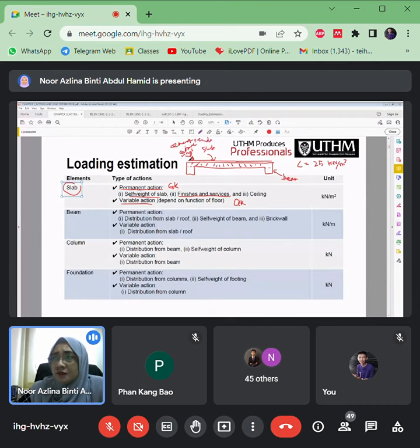So all of these give a load also to the slab, per area. So that's why we have to consider the finishes, and also services. Maybe this slab also has piping inside of it, and then we also consider the shielding. Normally it will be hangings below the slabs here. So these are all examples of GK, examples for the permanent load here.